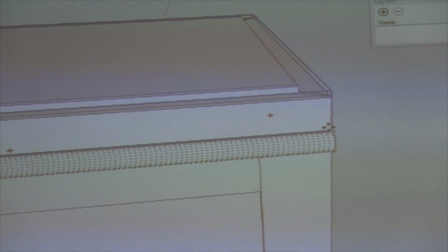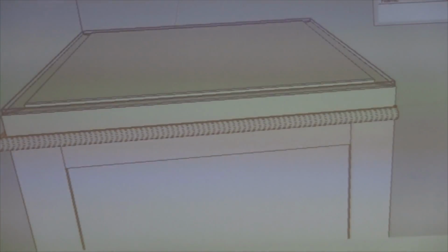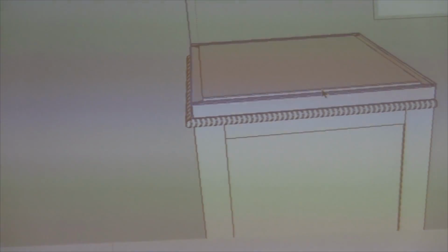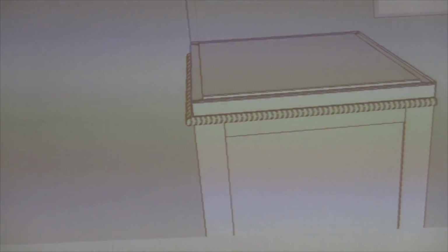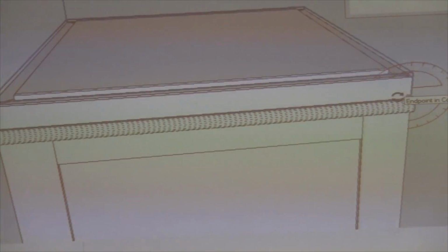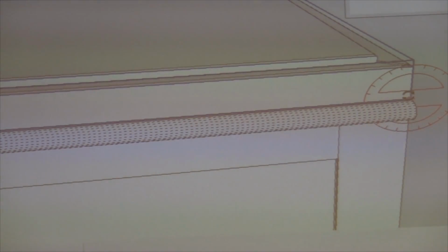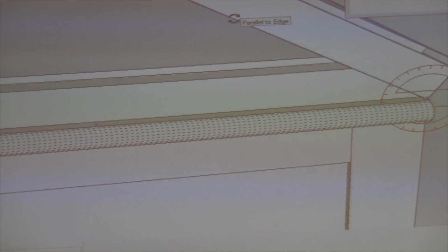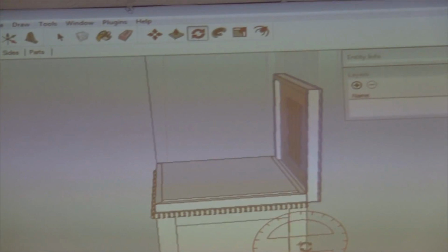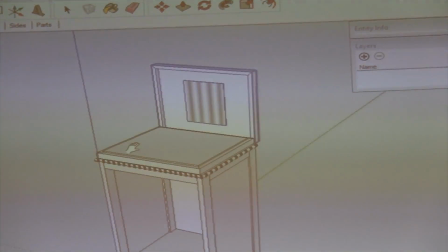So you can see I'm making a copy, but I'm going to drop it right on top of the other one. And now with 2 of them there, I'm just going to select the first one that it gives me, and I'm going to rotate it. So using the rotate tool, I'm going to rotate it just where the hinge would rotate, starting there along this axis and up 90 degrees. So now we have 2 lids.